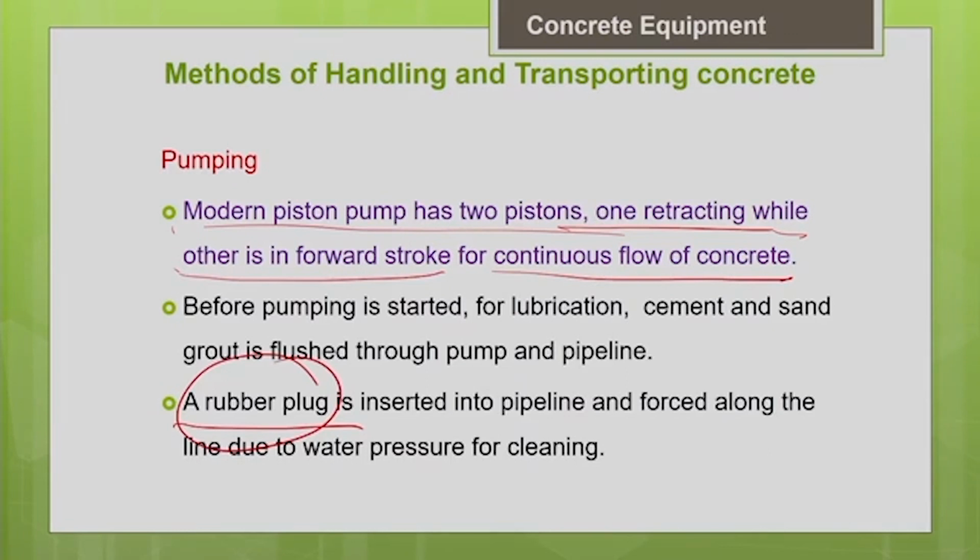So every time you do the pumping operation, before pumping I have to do the lubricating process, and immediately after the pumping I have to do the cleaning process. If you need a steady supply of concrete, pumping will be easier. Otherwise, if you need concrete in an intermittent manner, this process will be very tedious, because every time I have to lubricate and clean it. More effort is involved in that. So for a steady supply of concrete, pumping is the best option.